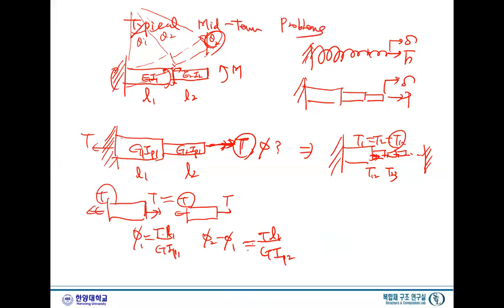So in this one, you can see that the concept is F equals Kx. No matter what, whether spring, beam, or torsion, it is all F equals Kx. But here we had moment equals, oh sorry, it's EI times the curvature.